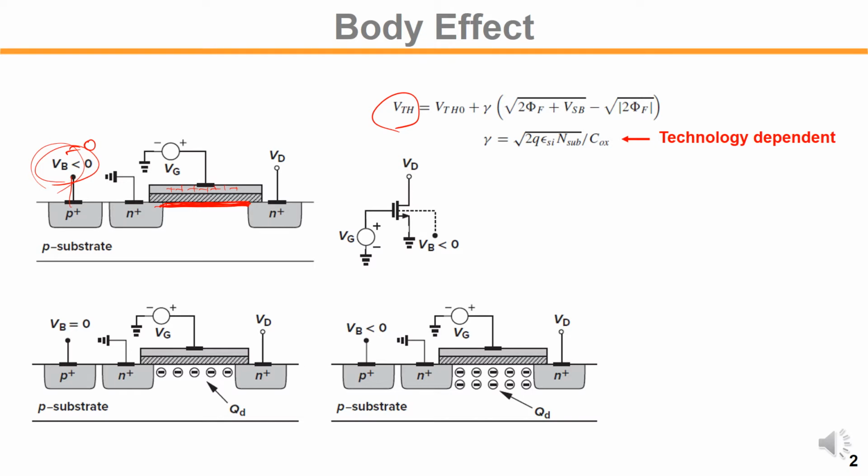So we are bringing the surface potential up by increasing VG. If we start from a voltage lower than 0 volts, then it will be harder to make the channel inversion here. This kind of thing can be visualized here. So for example, for VB equal to 0, increasing VG, let's say if the VG is equal to VTH, then we get the channel inversion like that.